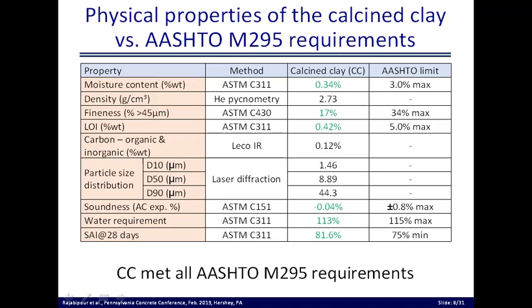The soundness is excellent in comparison with the AASHTO requirement. The water requirement, as I said, these are fine particles, so it meets the specification, but it's a little bit on the elevated side. And the strength activity index is 81.6%, which is more than the 75% that AASHTO requires. Now, I'm going to show you some strength results in a minute that essentially show that it's good.